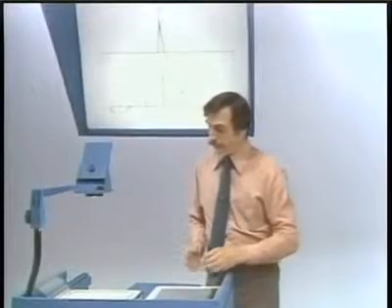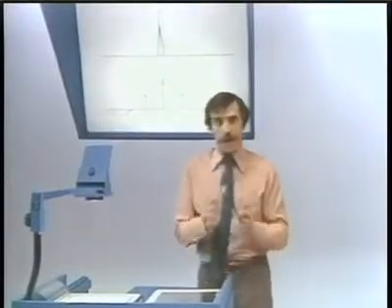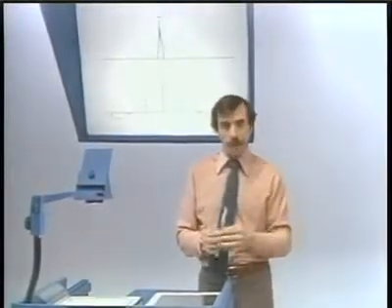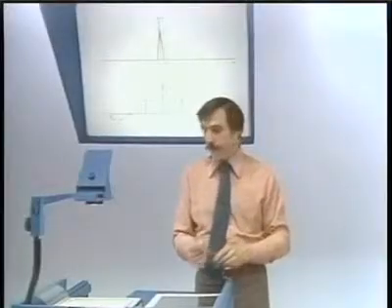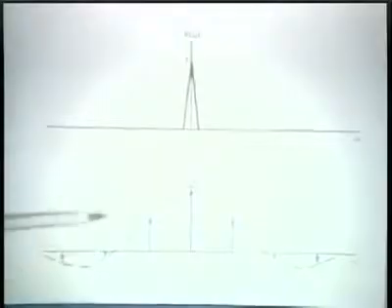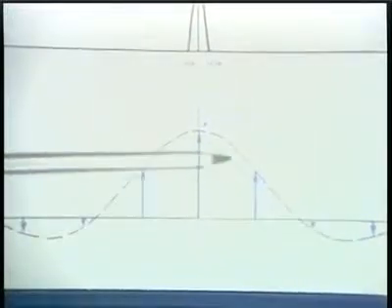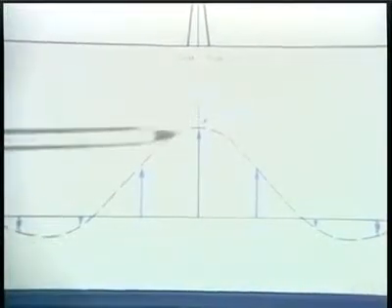What we have is a modulating signal which is a pulse train, basically a square wave. And as we've seen in previous lectures, the spectrum, or Fourier transform, associated with that is an impulse train. And the envelope of that impulse train is of the form of a sine x over x function.